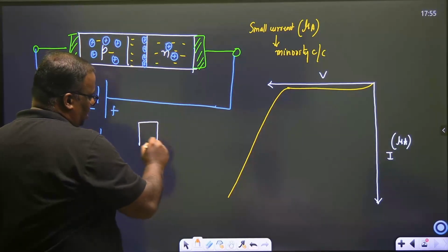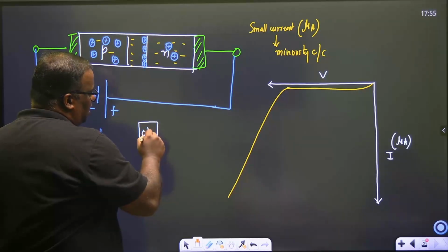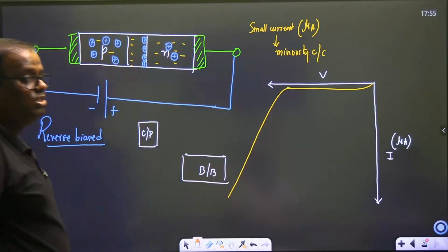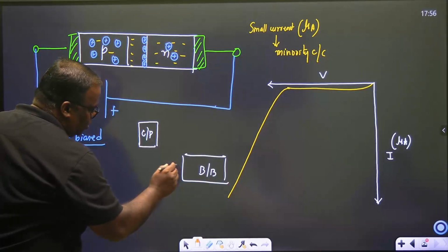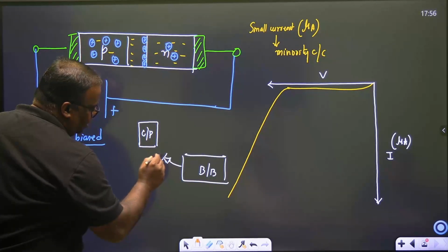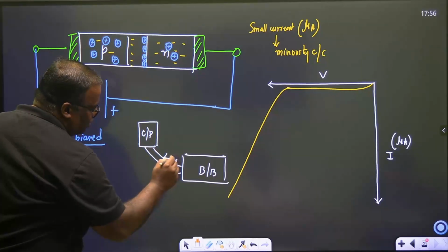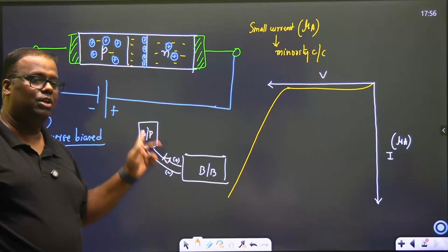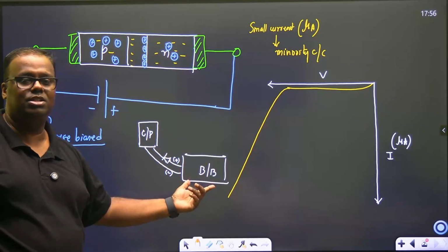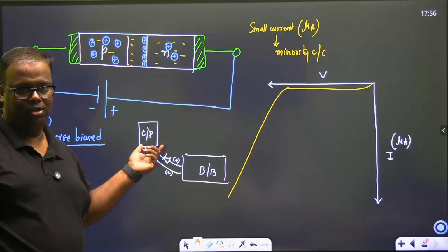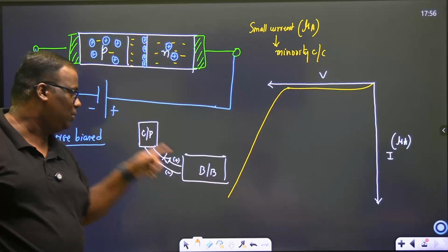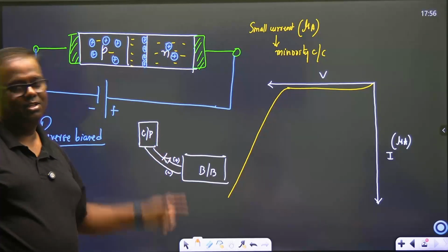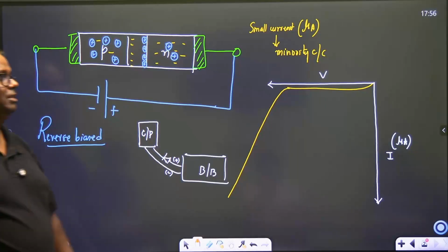So I always say this is the best way to understand. This is my cell phone and this is my battery bank. Yes or no? Your phone charges at 5.1 volt. So you will actually put one diode out here, and then you will connect it. This is the positive of your phone charging cable. This is the negative. So every time the battery bank is charging, the current goes this way. One fine day, the battery bank no more has charge in it, but you have a full charged cell phone. You can't expect that the cell phone will charge the battery bank, because at that time this diode becomes reverse bias. So it will not allow you to. This is how we do it.